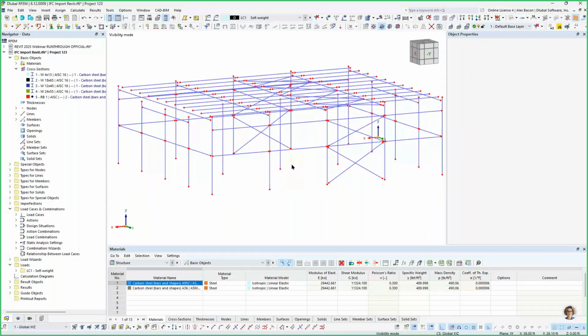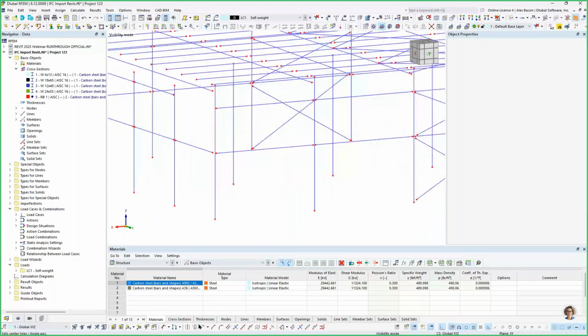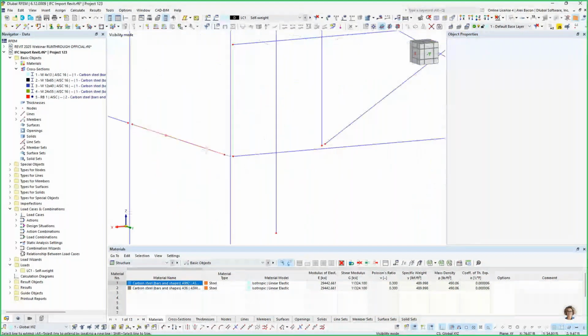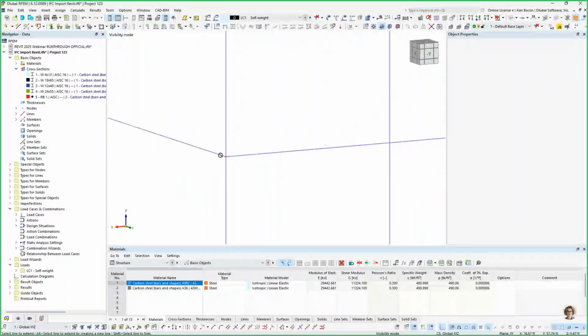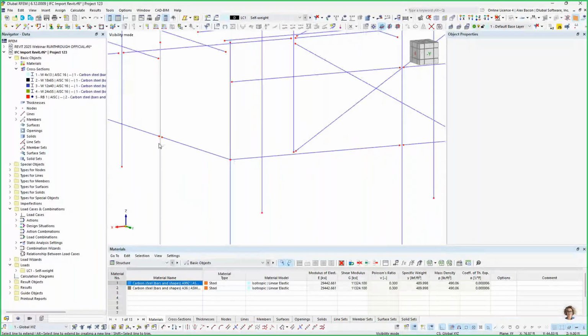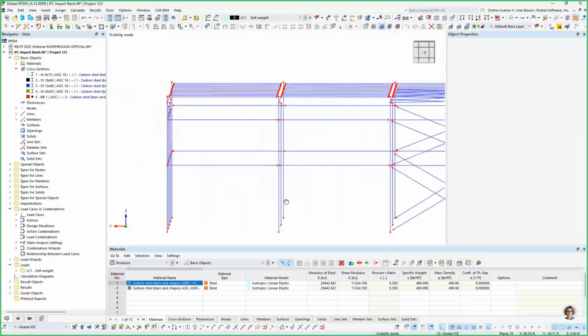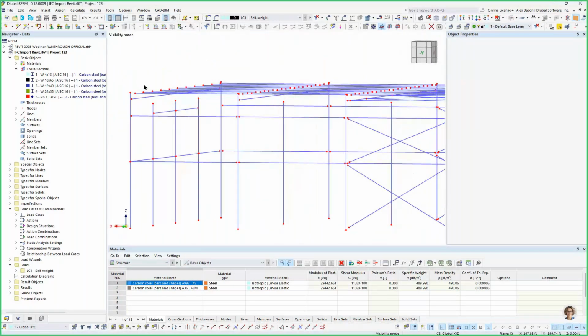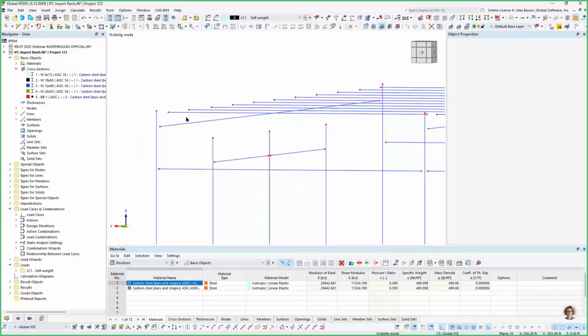The first option for connecting these elements would be to use the tool down here called the Extend Lines Graphically tool. So if I click on that, it'll essentially extend the lines, and they have to be in the same plane, but it'll extend them and connect them like so. So you could go around and connect elements like that. But the issue with this option is, what do we do with these coupling members up here connecting to my beam? They're not in the same plane.